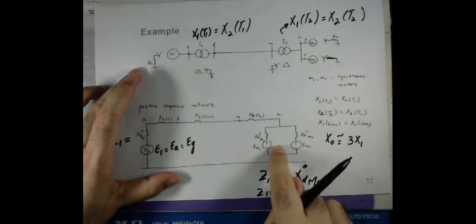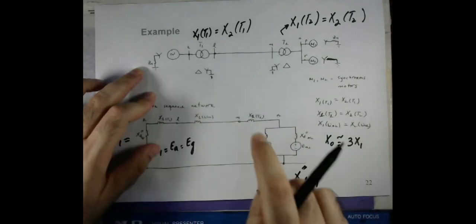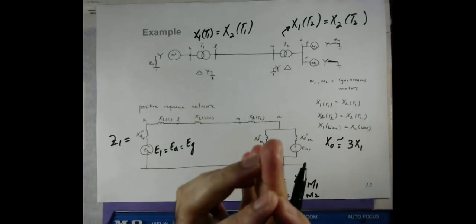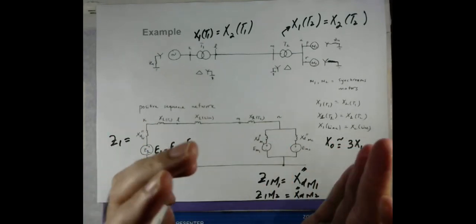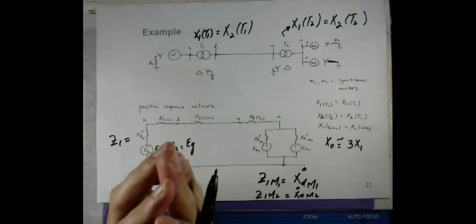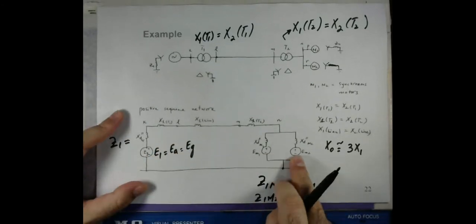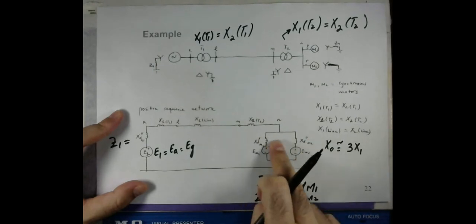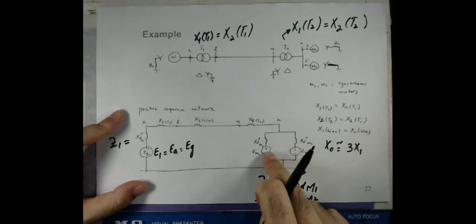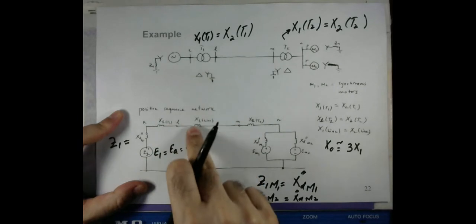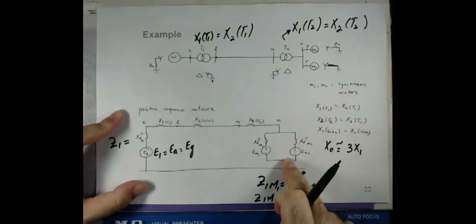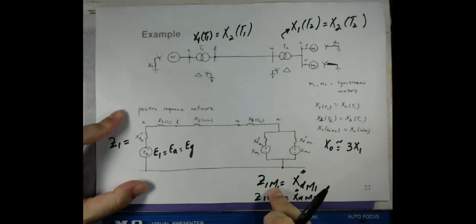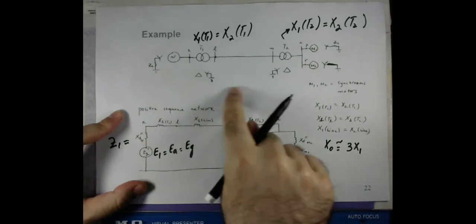considering also the voltages in the positive sequence network, because we have discussed before that in the case of the synchronous machines, although we didn't discuss the synchronous motor, but we discussed the synchronous generator. So the similar applies here, that in the positive sequence network, even if these are synchronous motors, we will consider the voltage source. So these two are the voltage sources for these two Y connected motors, and these are the subtransient inductive reactances, the positive sequence reactances, and the rest we have discussed.